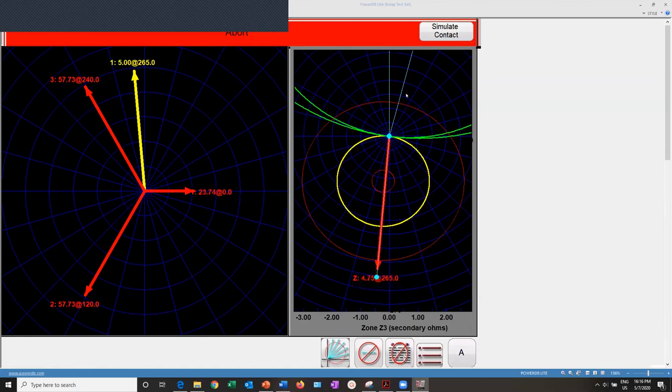As before, we are keeping the test angle constant, and we are simply waiting for the fault to get to the inside of the zone, and we will see the tripping happening there. Now, these red lines that we have here have to do with, let's say, the tolerances that we chose on the test. I didn't change those tolerances. I believe they are set at 5%, but I would have to check that.